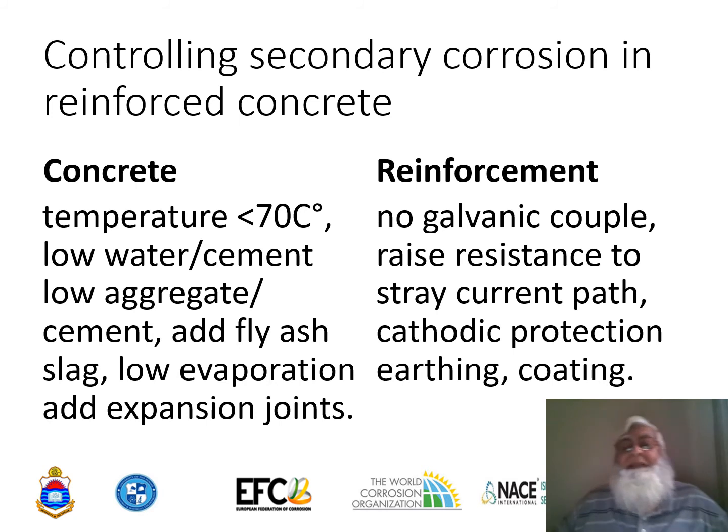If there's any galvanic couple, for example if you are using two different types of reinforcement with different galvanic potentials, then of course the one which is more active is going to get corroded at the expense of the other, so it's better to avoid any galvanic couple in there.